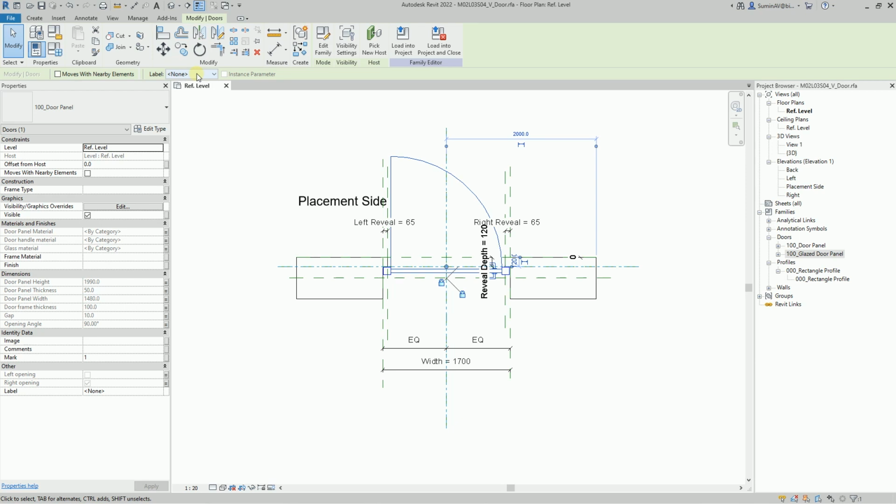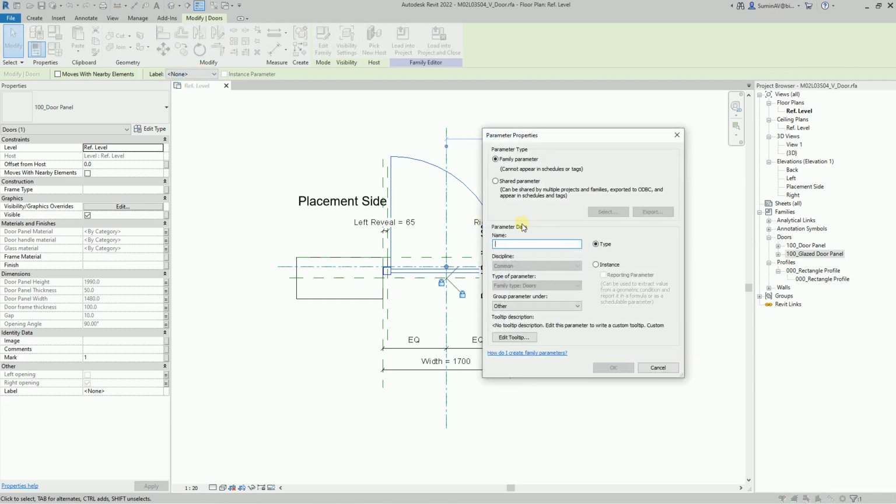But we can create a parameter in the parent family and specify it as a value. Then, through this parameter, we can switch between nested family types. Let's do it. This one will have the family type Doors type of parameter. Door is a nested family category that was automatically recognized by Revit. Let's call this parameter door panel.